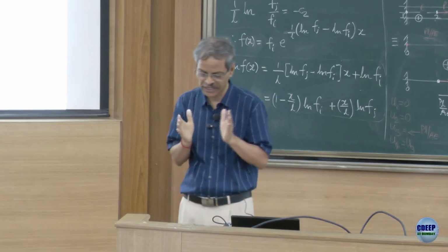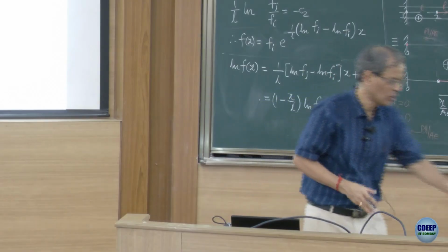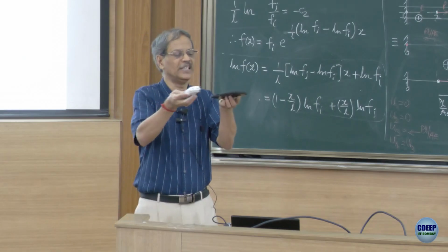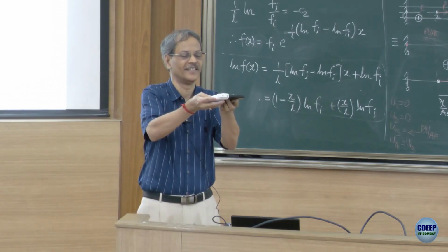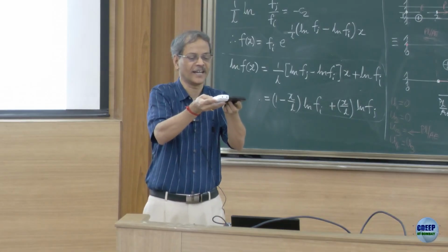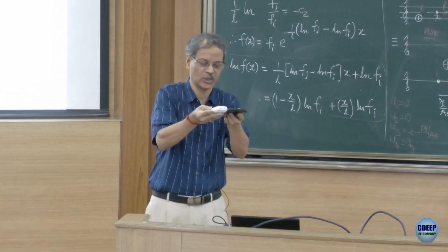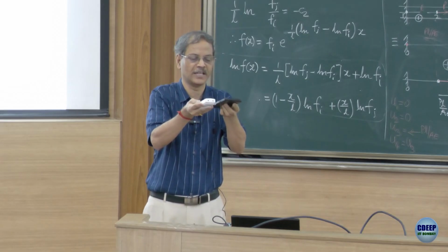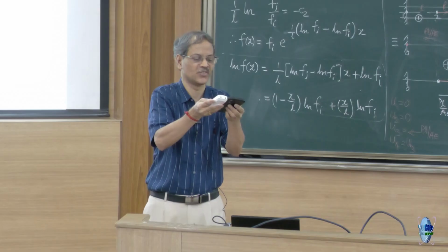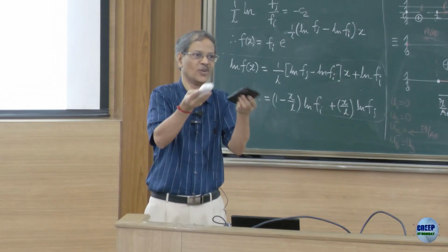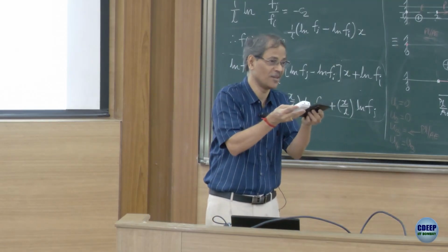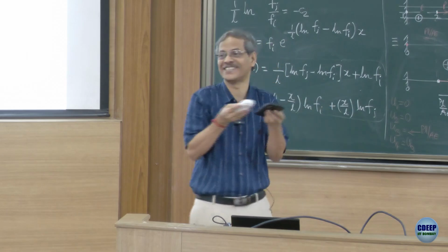Another important challenge we had was that if you look at two-dimensional elements, suppose two rectangular elements, when they join, irrespective of the number of nodes on this edge, across all the points on the interface, whether that point belongs to this element or this element, the field variable has to be the same. Let it be temperature or displacement or velocity or electromagnetic potential, whatever, that field variable has to be the same. And there are an infinite number of points on this edge.